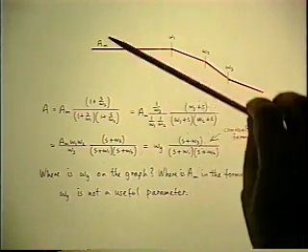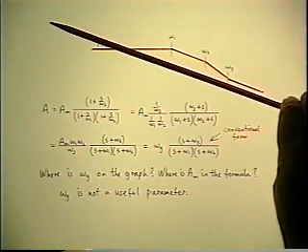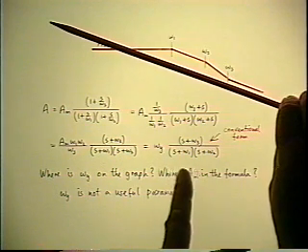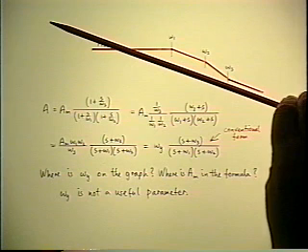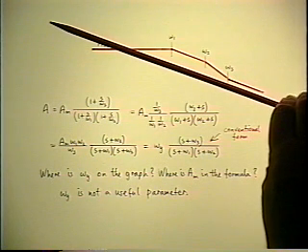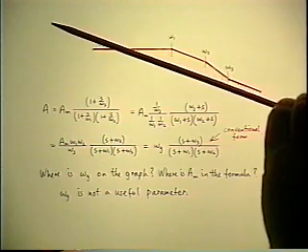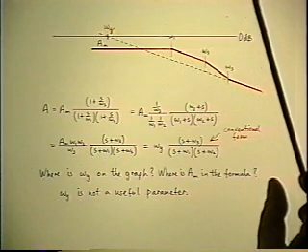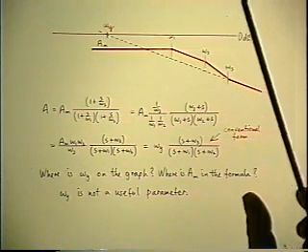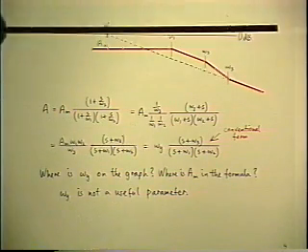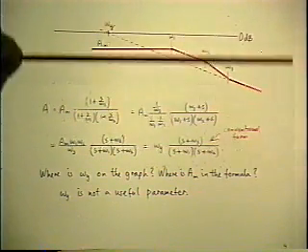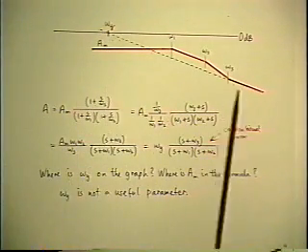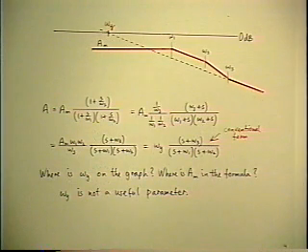So the infinite frequency asymptote, this one, is omega y over s, where the rest of the term has gone to 1 at infinite frequency. And so directly from that, omega y is the frequency where the infinite frequency asymptote crosses 0 dB. So there's one possibility. And again, I don't know where to draw that line without knowing numbers. It may be at any vertical position, but wherever it is, omega y is the frequency where that final asymptote crosses 0 dB.